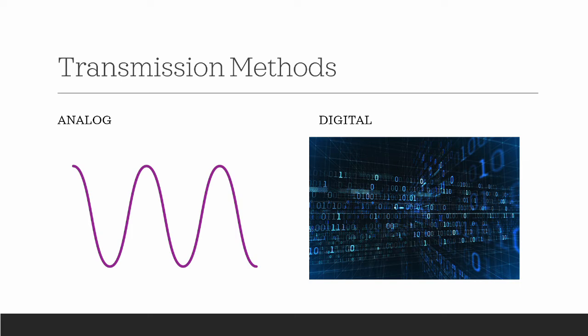As such, as your waveform changes, the broadcast waveform actually changes as well. And so, as I mentioned earlier, while we were talking about how selective and how narrow a bandwidth you can broadcast over, with analog FM transmission, that bandwidth actually modulates based on the program material. And so that can be challenging. Say if you're butting up against a TV station, or you're butting up against another channel that you're using, and you've got a signal that's modulating very heavily, that can create problems for you in terms of distortion and the effects that take place with that.